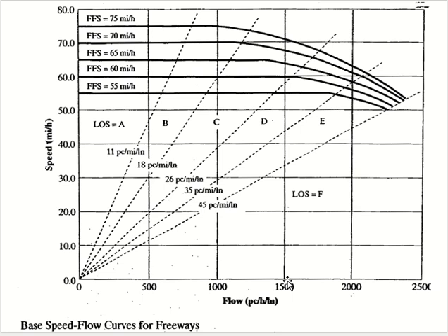Free flow speed. So if you know the free flow speed, you can plot the first point, right? What are the coordinates of the first point? Tell me now. X and Y. 0 and 65. 0 is the X value, so flow is 0 and 65 is the Y value. Clear? After 65, how does the curve move?